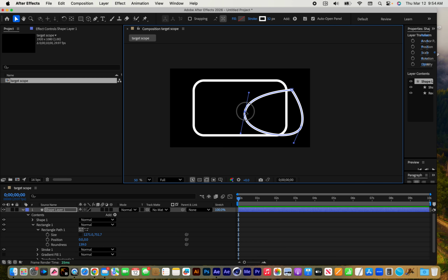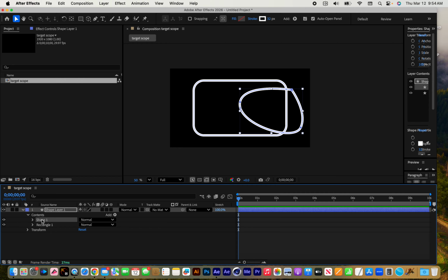It's defined by points and curves or splines, okay? So that's a Bezier shape. And notice that with the Bezier shape, under the layer here, it has a path group, but there's only one property there called path to animate that path shape. So again, it's not defined by numerous parameters, it's just defined by one singular path property.